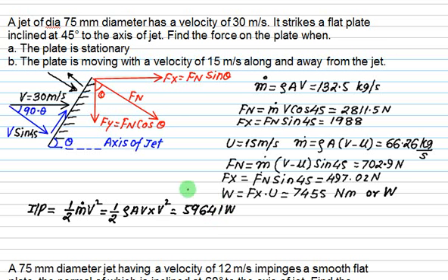This one is output power. So what is the efficiency? Output divided by input. That is why we will never use the flat plate, because the conversion efficiency is very less, only 12.5%. Your objective is to increase the value of this efficiency. That is why we have a modification. That is why we are studying the curved symmetrical, then entry at center, then entry from one end, and we always try to modify the efficiency.